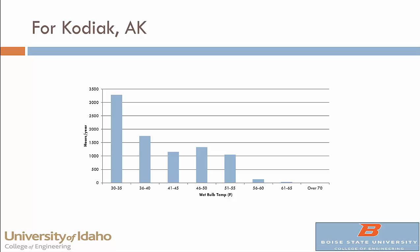data for Kodiak, Alaska. We visited there in the summer of 2013, and I went through this process for the TMY file for Alaska, pulled it out, added a column for wet bulb temperature, and then did a histogram on it. And so what we found here, for a typical meteorological year, the wet bulb temperature in Alaska was between 30 and 35 degrees for about 3,300 hours of the year. So well over a third, close to half. And then another 1,700 hours a year at 36 to 40, and so on.